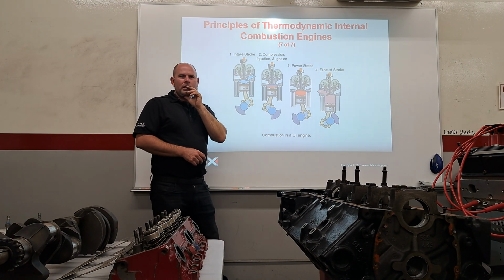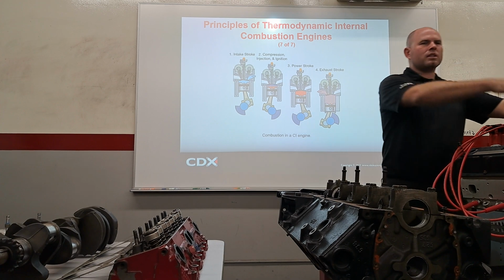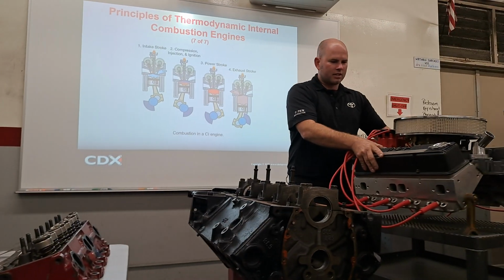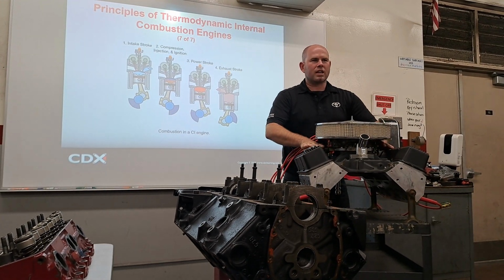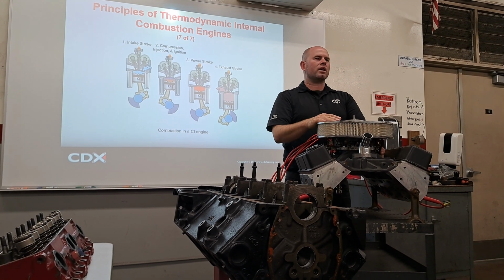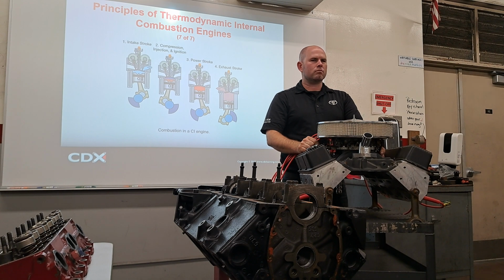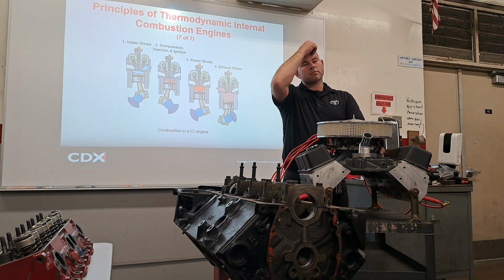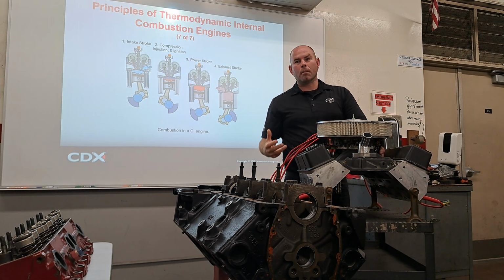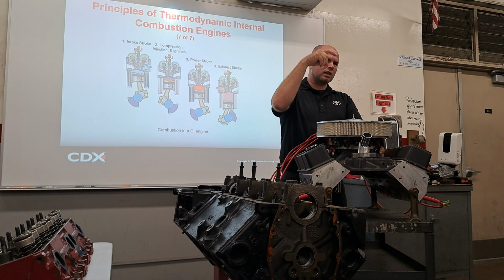And this is why. If you backed up to a gas engine like this one, this has the carburetor. Roberto, take a peek at this. This one, because it has a carburetor, air comes in and fuel mixes with it. And then what gets sucked in on the intake stroke on this carbureted engine? Air and fuel. Cool? So in the intake stroke, there's already fuel. Then we compress air and fuel. But it doesn't light until we ignite the spark plug, and then that ignites, right?